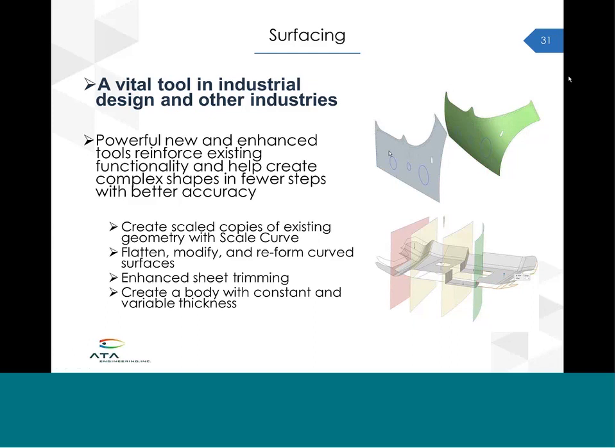You don't have to worry about how these objects may be projected from the tangent plane to the ultimate curved surface. And because you're now working on just a single plane, you can do all your sketching in one go. And then using the original parameters of the originally curved surface, you can take this flat sheet body and reshape it to match the original curvature of the original sheet.